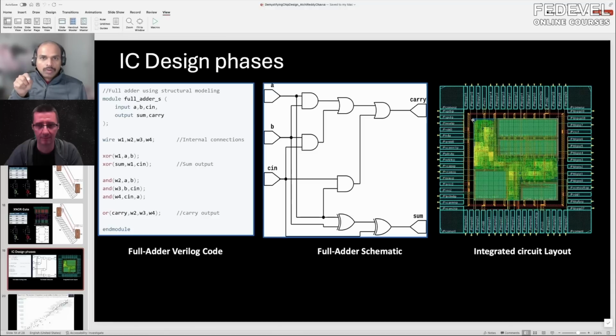But the longer the route, the more time it takes and the higher the resistance. That limits the performance at which I could operate this chip. The auto-router would find out that this doesn't meet the specification. Also, because there are so many components, it would take years and years if everything had to be connected manually.